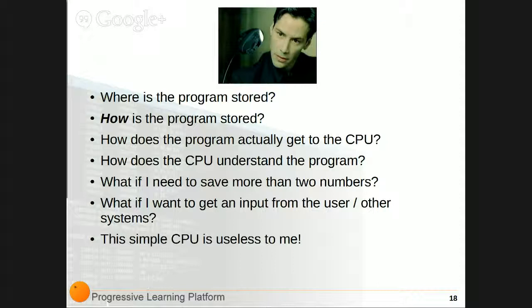You've seen an instruction where you load a number to a register, immediately from the instruction, right? So load number 5 to register 1. That's immediate loading. The other way is to do a memory load, load from memory from here, which you'll see later. So that's how you actually get data from outside of the CPU and outside the program.